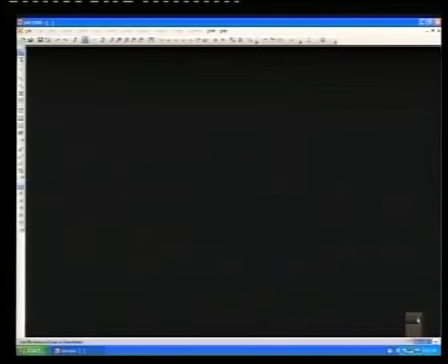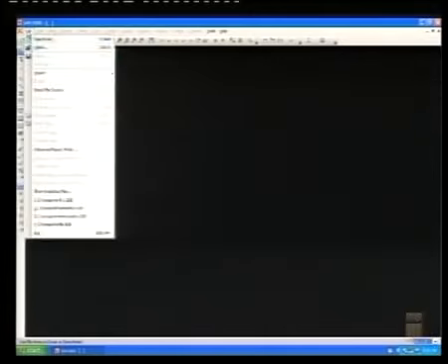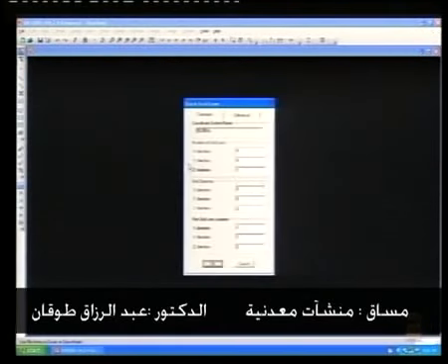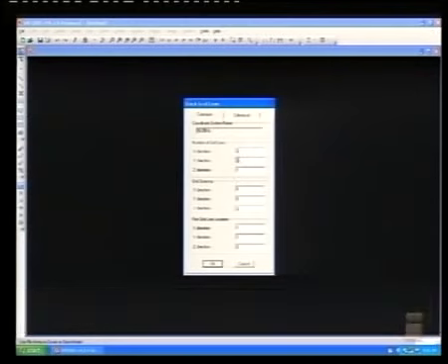The units are kilonewton meter. File, new model. Let us take grid only. We have in X direction 3 grid lines. In Y direction, there is no Y direction. In Z direction, we have 2 grid lines. What is the spacing in X? The spacing in X, 9 meter. And the spacing in Z, 4.3.